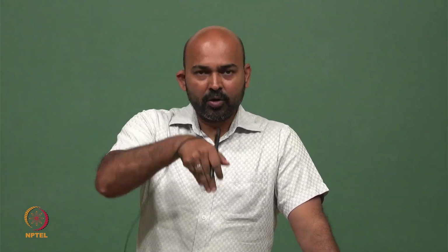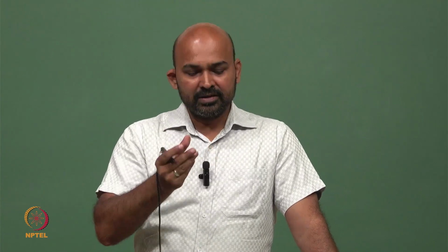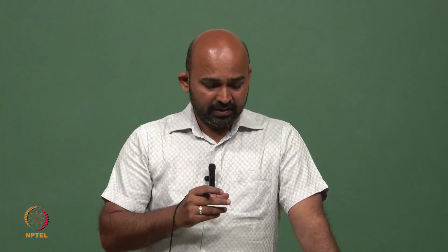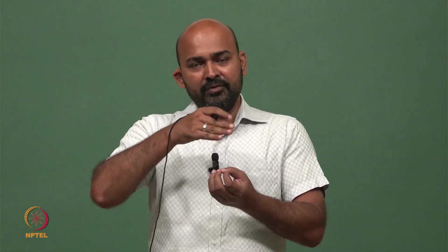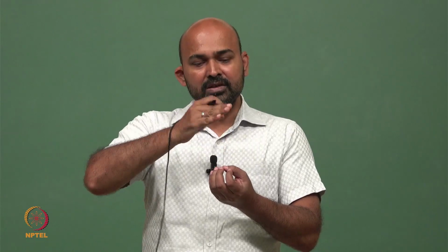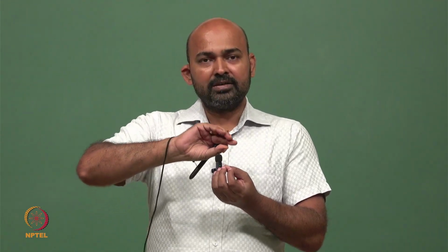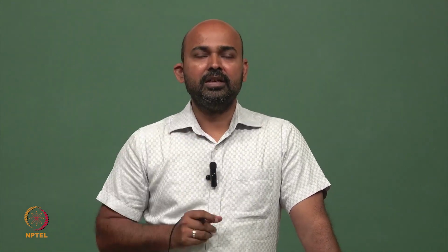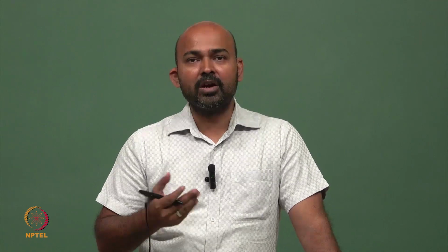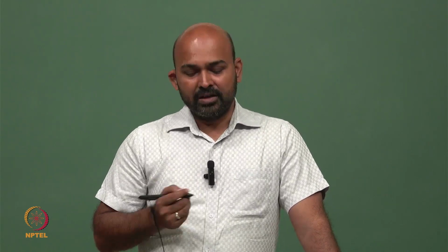And there are two types. One is the bonded fin, where we take the fin and bond it on the piece of metal, and this is called the bonded fin heat sink. The other one is the folded fin heat sink, where we have these fins and we fold them again, so that a single fin now has double the area of the earlier one. In this way we can increase the surface area of the total heat sink, and this can effectively evacuate the heat from the devices, the electronic devices.